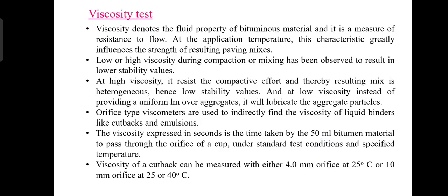So the next comes the viscosity test. The viscosity denotes the fluid property of a bituminous material, and it is a measure of resistance to flow. At the application temperature, this characteristic greatly influences the strength of resulting paving mixes. Low or high viscosity during the compaction or mixing has been observed to result in lower stability values. At high viscosity, it resists the compactive effort and thereby the resulting mix is heterogeneous.